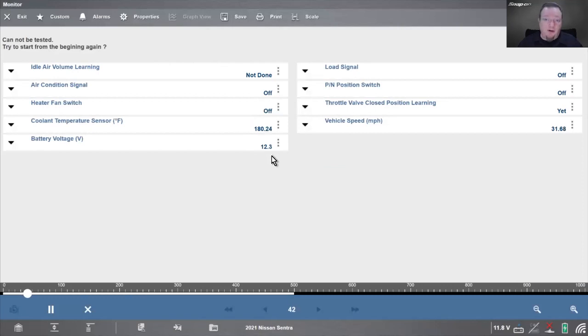Battery voltage is too low. I can tell you that right now. And the vehicle isn't supposed to be moving, right? So dummy data is going to throw that test off. So I need to make sure that I meet all the parameters. Otherwise, it gives me that error.